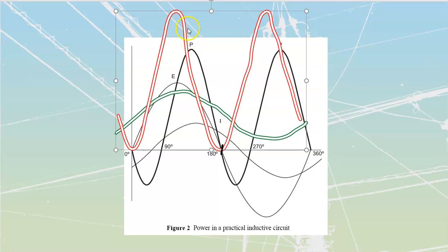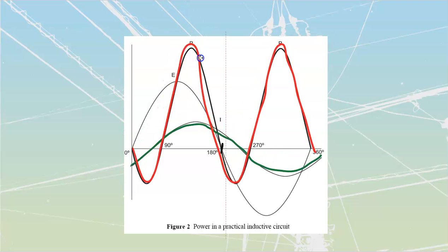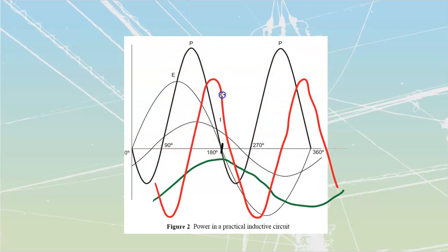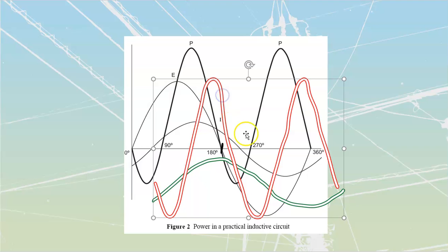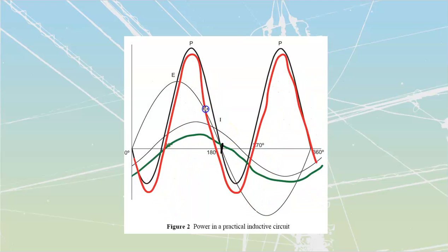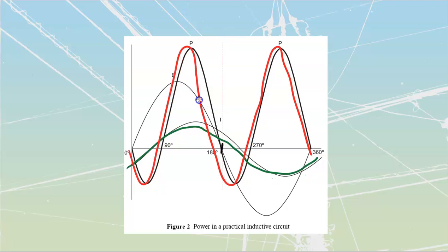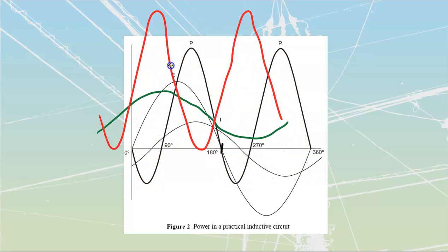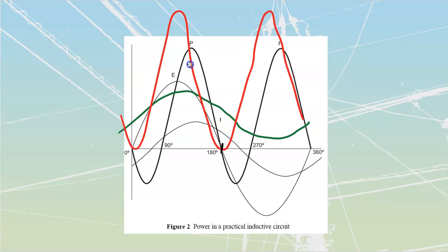As we move into a more inductive type of system, all that's happening is that my positive power is moving down and across until eventually it would get to the point where it would be 50-50 across, at a theoretical inductor. It's just shifting. That's all that is happening. And if something is shifting, the great news is we can usually find some way to shift it back. How do we shift inductance? Well, we're going to get to use capacitance. So we can shift inductance back, and we can actually start putting everything back to the way it was supposed to be.